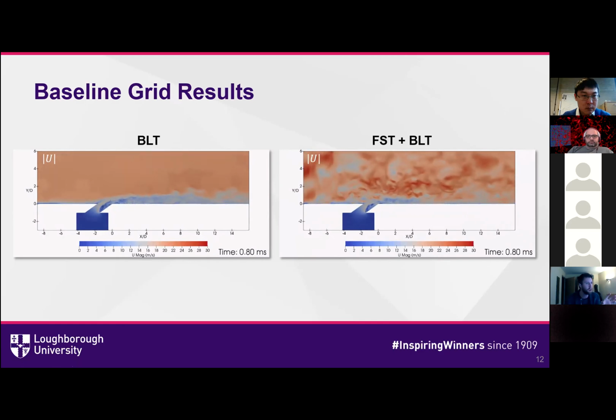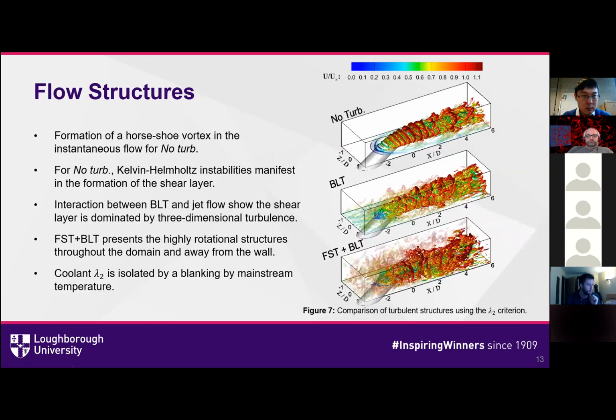The separated region provides a turbulent behavior that then progresses across the near wall trailing edge of the coolant hole flow. And as you can see, this is fairly consistent to about 3-4 diameters downstream, and then the elevated free stream turbulence takes over, and we'll see some of the effects of this later in the presentation.